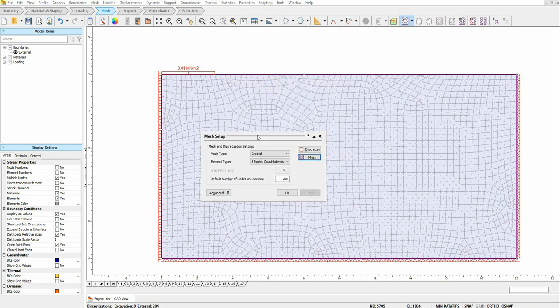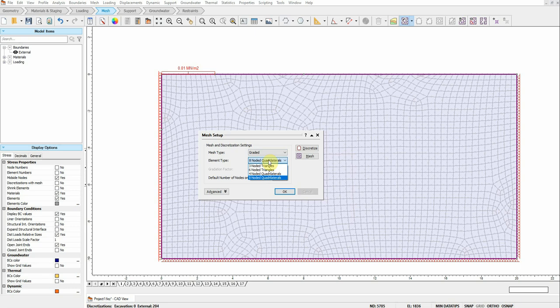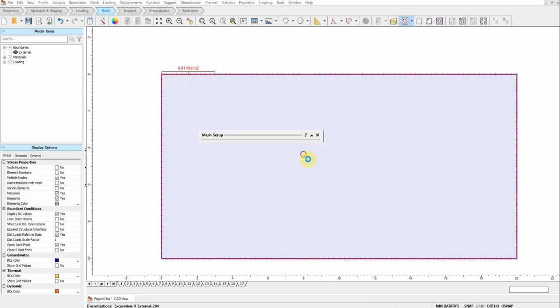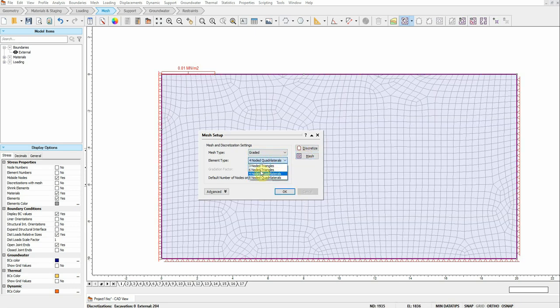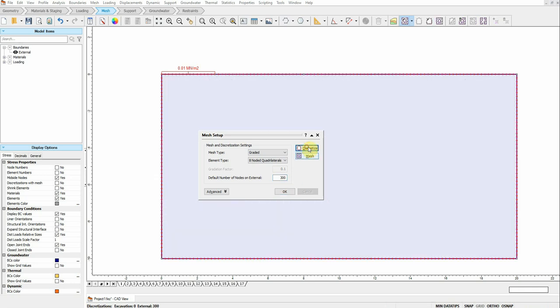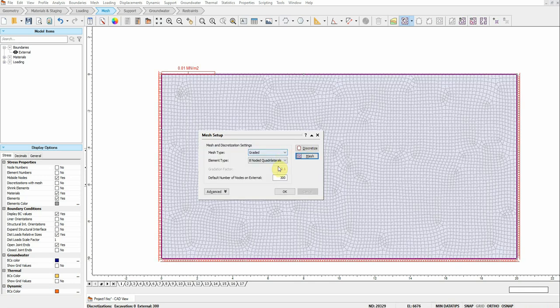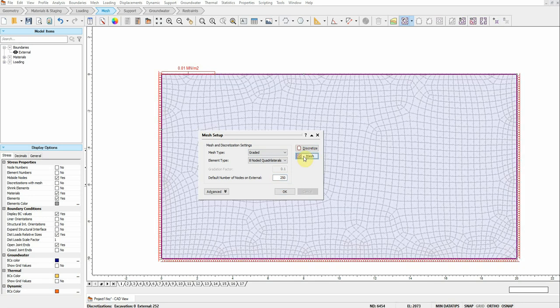Mesh. This is how it looks if we change this to 4. I just want to show you how it looks. As you can see, we don't have any surface topography except one single layer here. In this case, it will be fine if we make it finer. That's fine too, but I think that's too much. Let's make it 250. Okay.